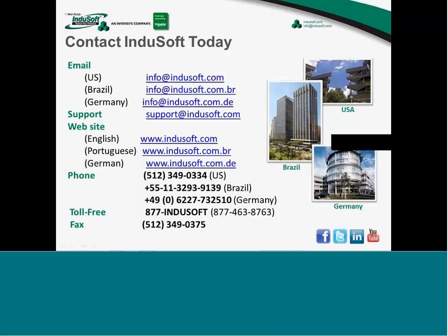So there is a quick question there, if I can address that real quickly. Configuring a server in the CX, or really any PC, because that's just a PC, is an endpoint required if no security is required? The answer is no, but I don't recommend it, because an endpoint also helps you with auto discovery. So there are many benefits to it, and for most people's implementations that I've seen of OPC, it's really not a big deal to configure the endpoint. So you can run it in a classic way without the endpoint, but you lose a lot of the benefits of DA or UA.